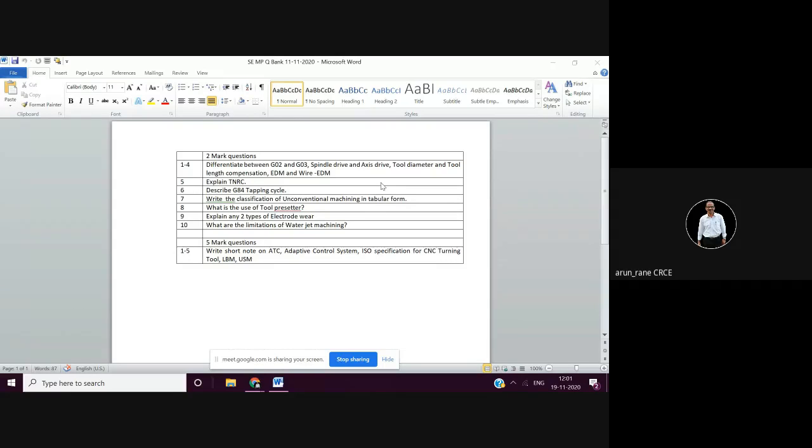So you just directly put it in the tool magazine, and then you enter that tool length and tool diameter in the tool library in the offset page. This entry can be done while the machining is going on. It can be done in the background. So the time is saved.